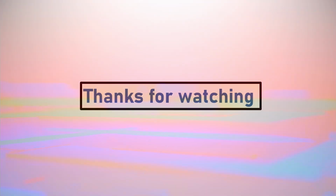I hope you understood the basics of the 2 x 4 decoder, 3 x 8 decoder, and 4 x 16 decoder. These are the three basic decoders. We have other decoders too, higher decoders like 5 x 32 and many more. Like we know, if you pass n inputs, we are going to get 2 power n outputs. There are many, but these three are the main ones that we are going to use if any application needs them. In the general sense, these are very simple.